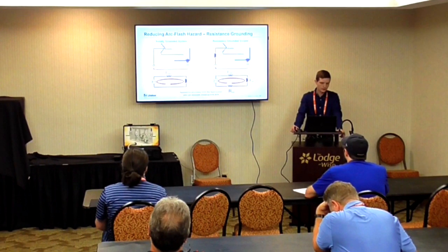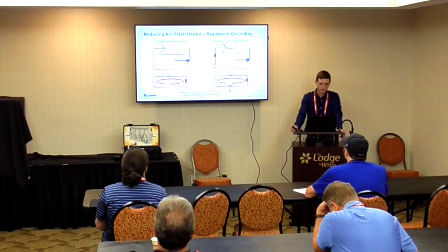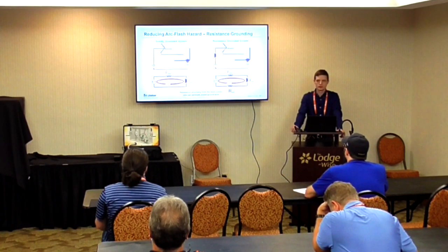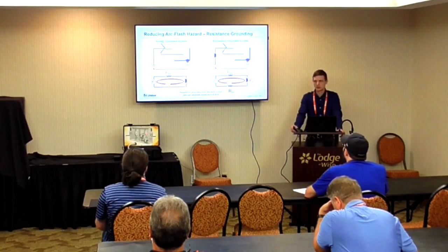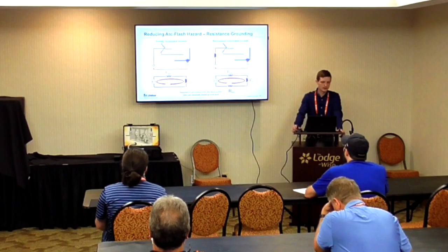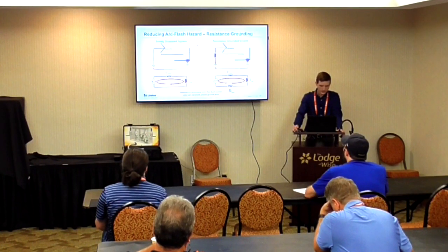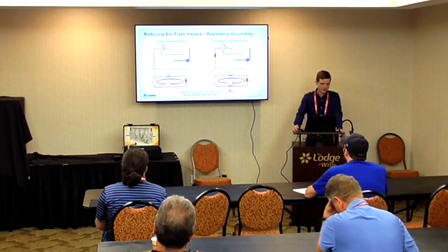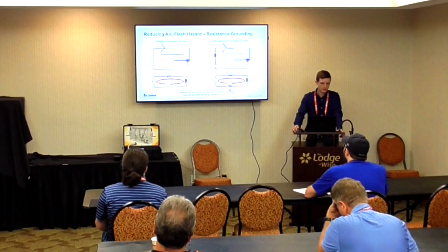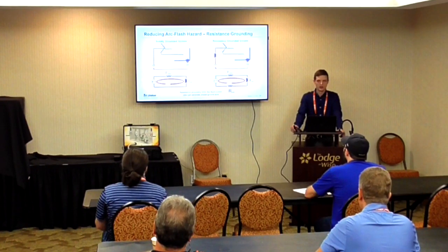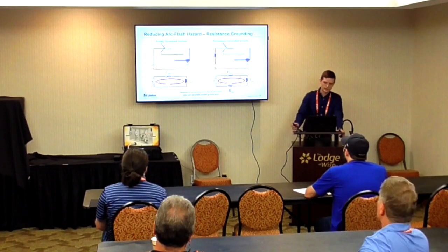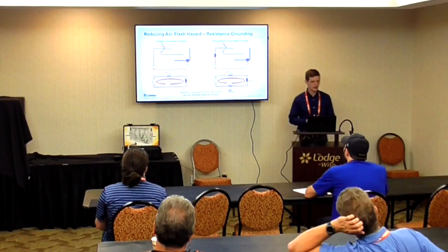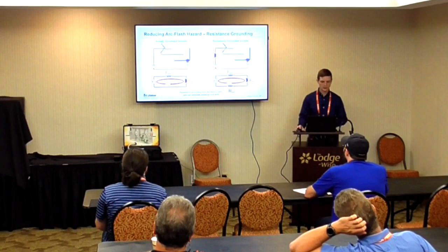So speaking of the different grounding systems, which is why I bring this up, something that you'll start to see most commonly now, ungrounded systems is a bit of an old one, so I'm not going to talk about it too much. But you'll see a lot of solidly grounded systems right now. And essentially what happens here is as soon as you have a phase that goes to ground, you now have a low impedance to no impedance path for current, and that's going to have a very high incident energy or fault current.